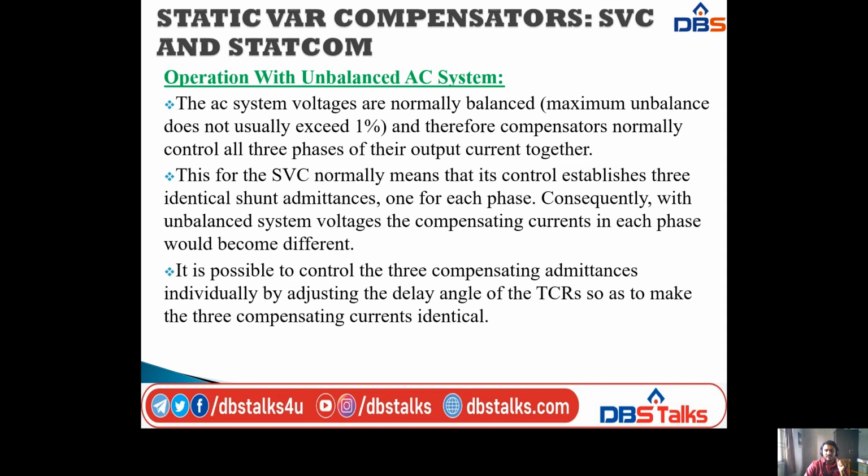Therefore compensators normally control all three phases of their output current together. Thus for the SVC, this normally means that its control establishes three identical shunt admittances, one for each phase. Consequently, with unbalanced system voltages, the compensating currents in each phase would become different.